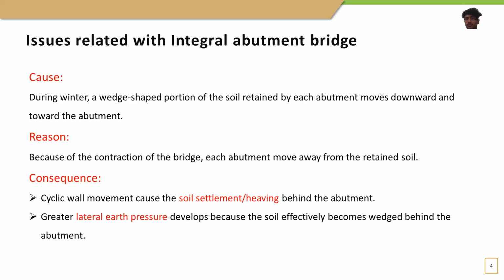Also, because of the active and passive movement of the abutment towards and away from the soil, in time it will cause soil settlement and soil heap behind the abutment. As a consequence, the lateral earth pressure will start to build up behind the abutment, which is also called the soil ratcheting effect. So, in order to understand this complex soil structure interaction mechanism, I have done two tests using the